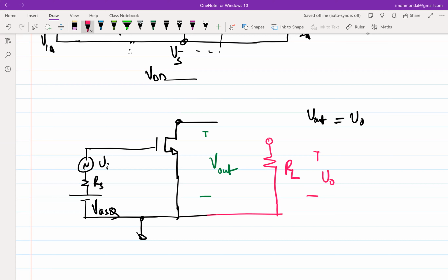Is the question clear? We cannot put the RL between the drain and VDD. You always have to ensure that one terminal of the RL is grounded, which means you have access to only one. So now I want to still get an amplification across RL. So what should I do? We come to a capacitor, right? So there is a reason why people connect a capacitor. What is the thought process behind it? What is the first step that you should respect?